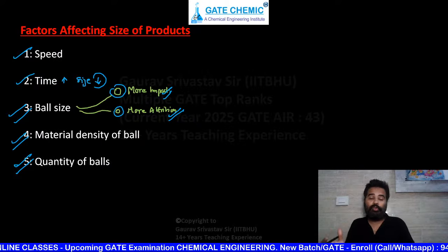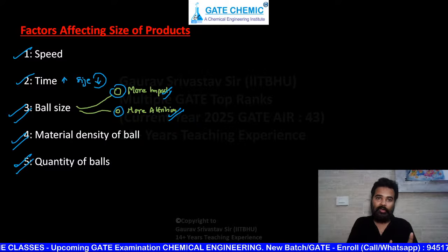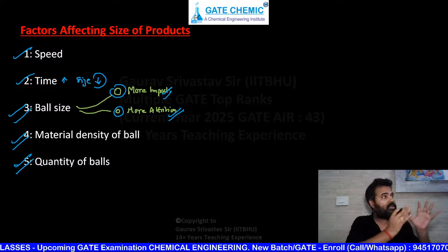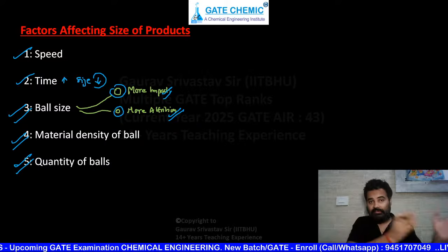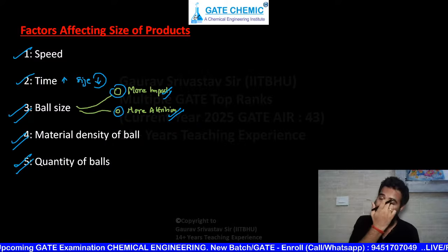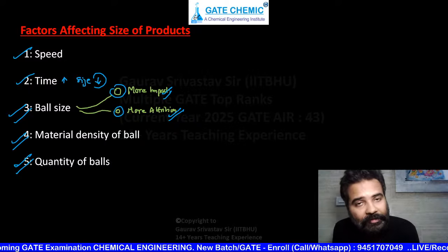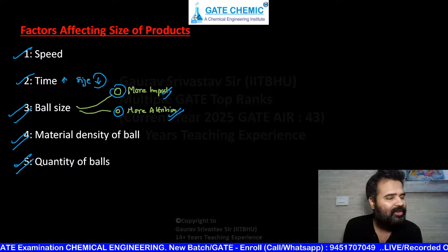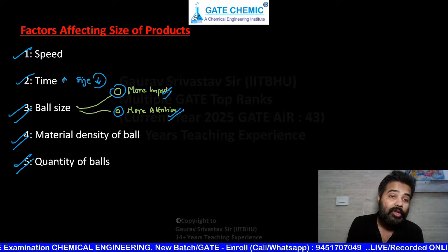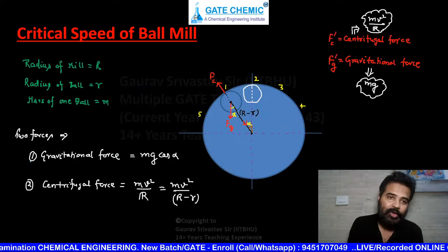For how long are you running it? For 10 seconds or for 10 minutes, with only 20% ball, or 10 minutes with 30% ball, or 40 minutes or 10 minutes with 30% ball. In these different cases, definitely the product size is not the same. Even if you feed with the same feed size, the product size is not the same. Okay, so these are the factors affecting the size of the product.